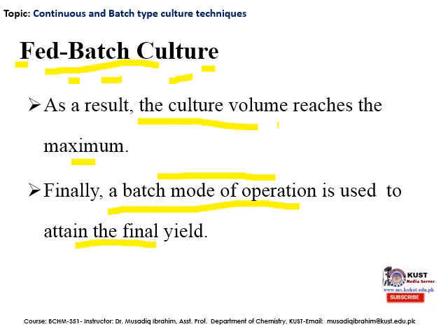Now in case of the continuous culture mode, there is a continuous addition of nutrients through the whole run of the fermentation process, as well as there is a continuous removal of the effluents from the fermentation tank during the whole process of the fermentation technique.